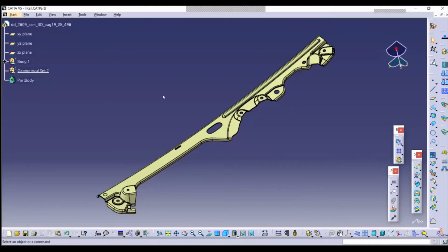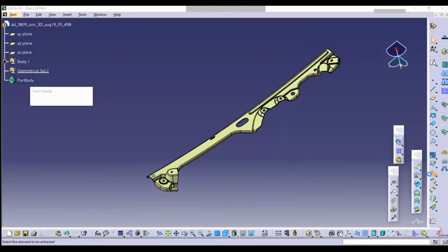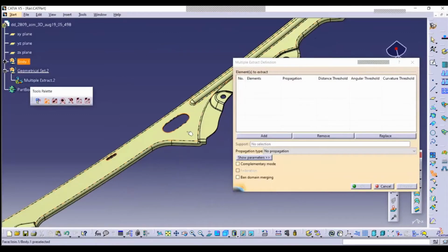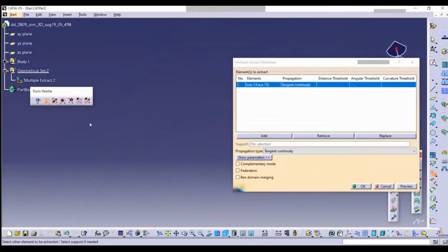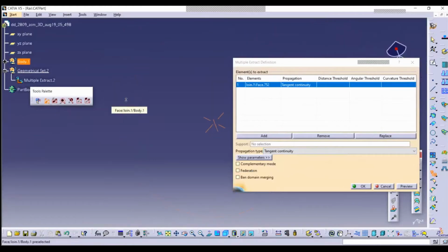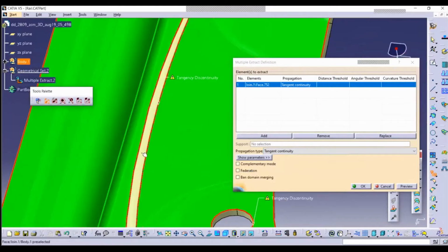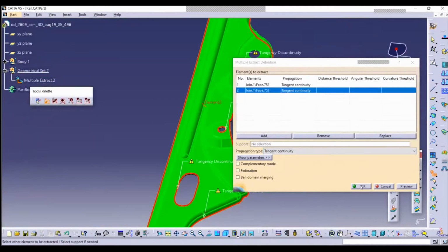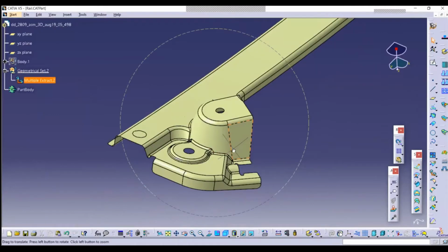As I said, I start with, in this case, a solid model. I've created a geometry set where I'm going to do all of my manipulations. To start, I want to extract one side of material so that I can perform my analysis. This is what I'll do now. Looks like there's a bit of a tangency issue here, so I can just use the multi-extract to pick out that surface. Say OK. And then I can also hide the 3D just to make it a little bit easier to see. So now I have the surface model representing the component.